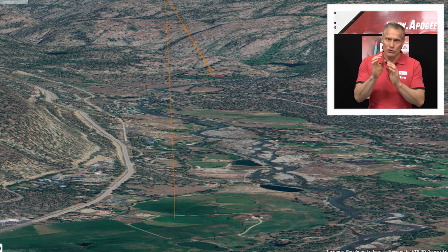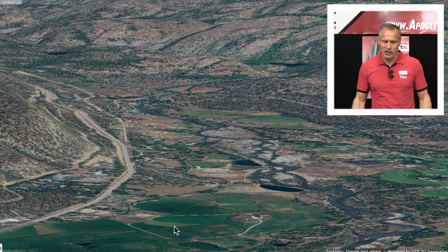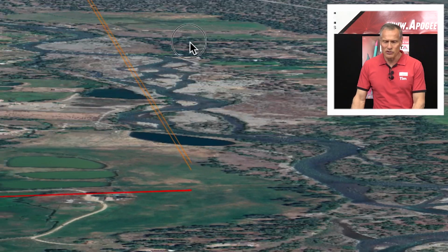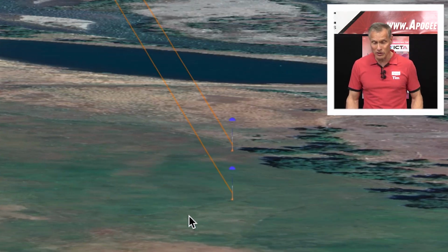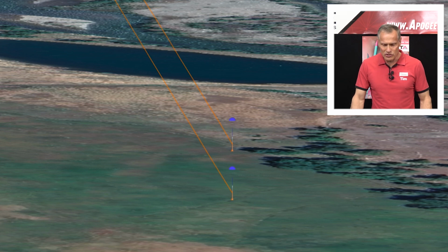Since the spill hole is so small, they don't start diverging in their flights until about this point here. And now you can see that one rocket is going to land just a little bit closer or a little bit faster than the other one. We're just zooming in on it here just so we can see the parachutes coming down. You can see one is lower in the sky than the other, and it's not much. Like I said, the big advantage of the spill hole is that it stabilizes the chute. If you want to fall faster, it's probably better to use a smaller parachute.